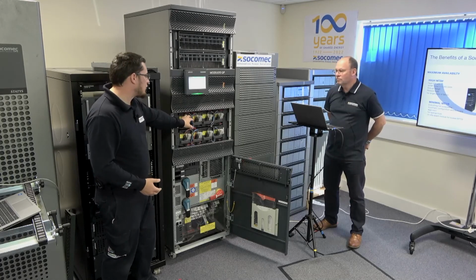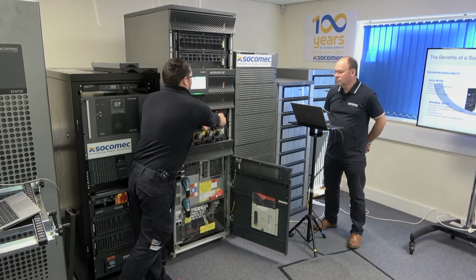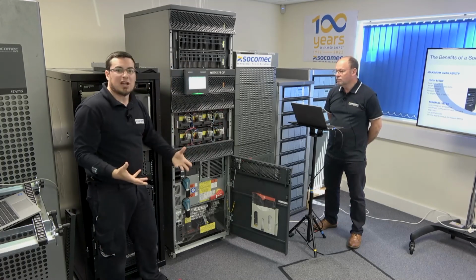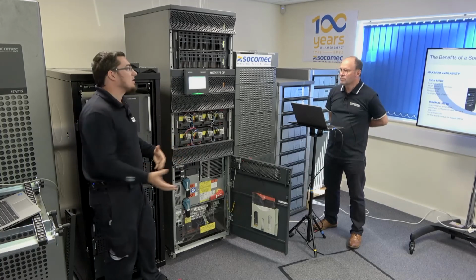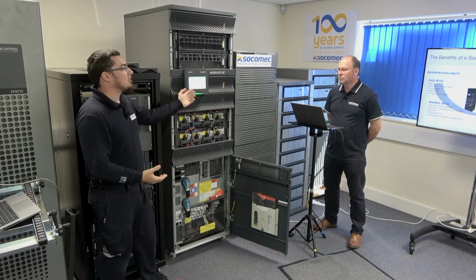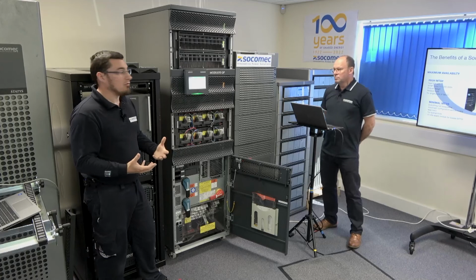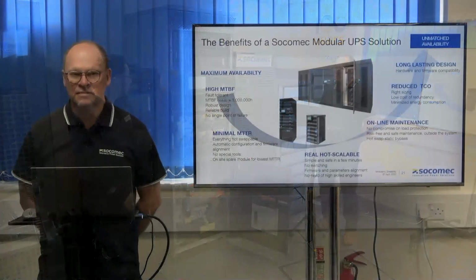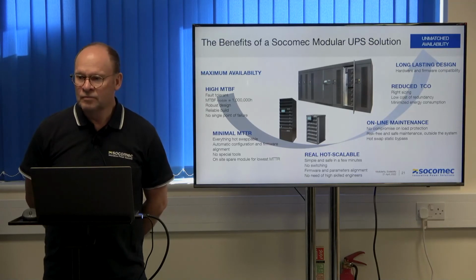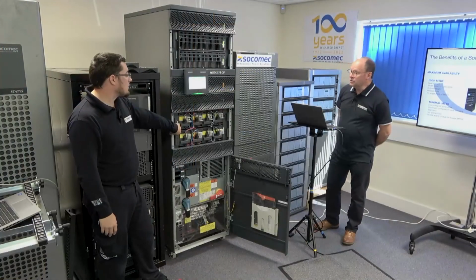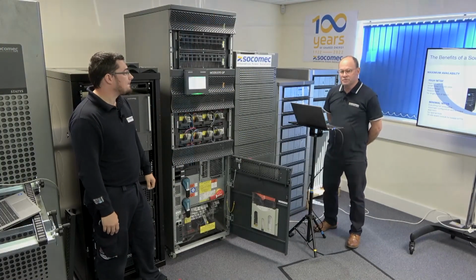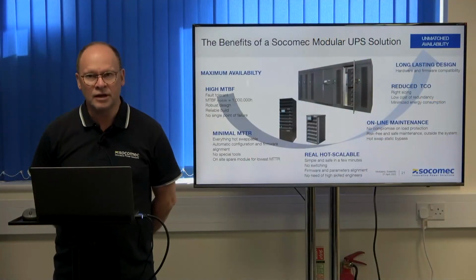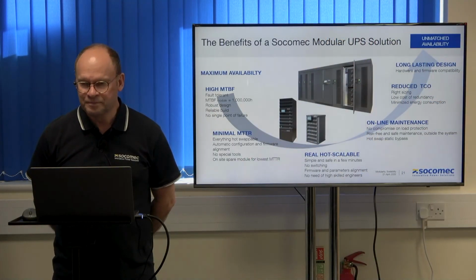So we could open one set of batteries up, carry out maintenance on those batteries, change them, replace them, do impedance testing, stick them back online. We're still on inverter. We haven't had to put the load at risk. It's still got battery protection from the remaining batteries. Short of time, but it's there still. So these are lead acid batteries, and we've got lithium ion options as well. So it's lithium ion ready. We've supplied systems with lithium ion batteries, so if you need that, they're available also.